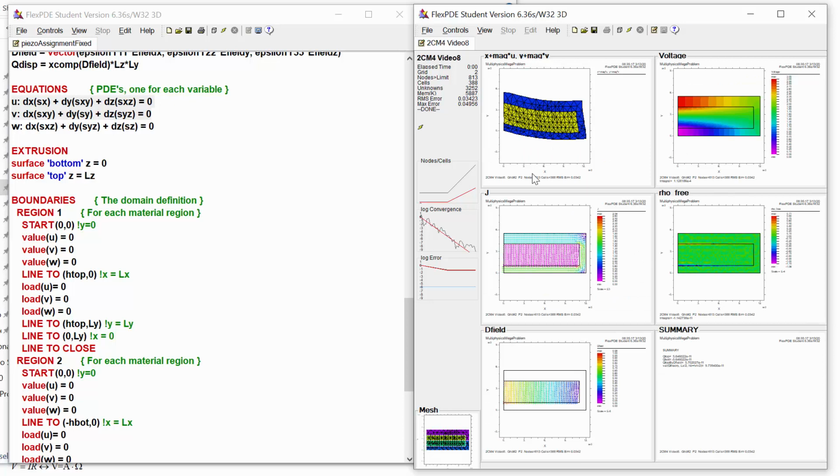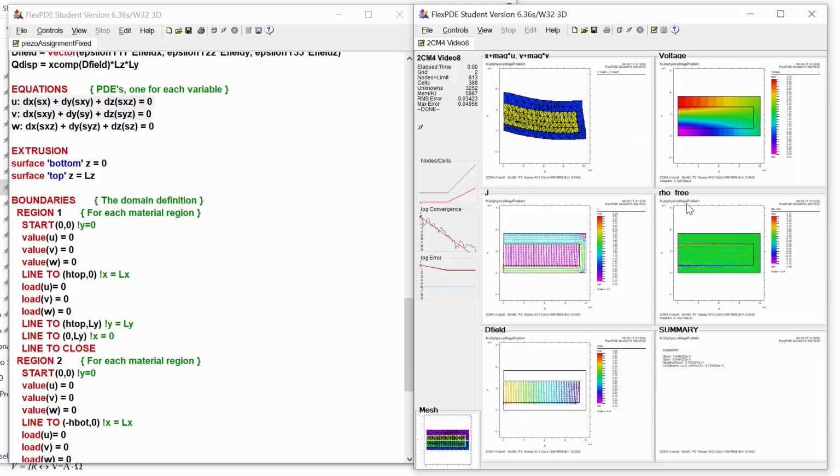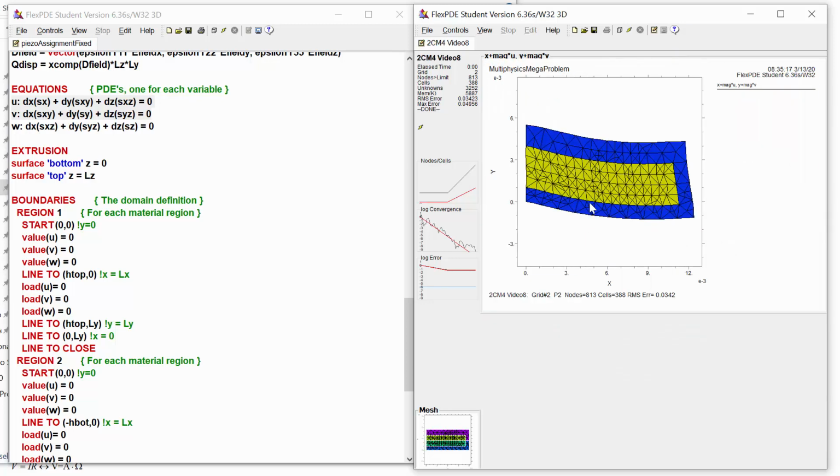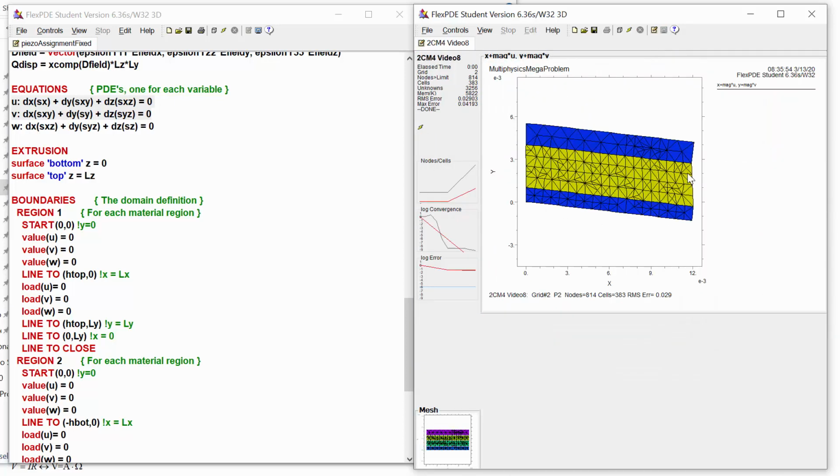From the displacement that we've got set up in here, we've ended up with an interesting kind of bending down effect. This primarily seems like it is to do with, let's see, it looks like it's mostly an XY shear that's happening, but it's non-uniform, so it changes as we move from one piece to the next. What if we get rid of LT? This looks like a much more pronounced shear strain in this. This is a negative XY shear strain because per positive step in X, we've got a negative displacement in Y.